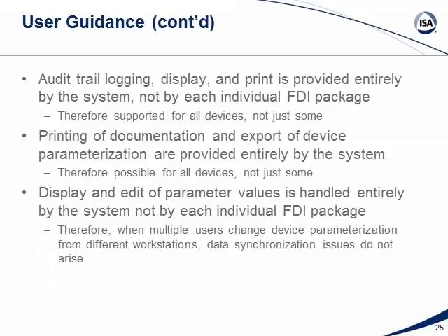Now there are a lot of other strengths to consider, and other process requirements. Audit trails are very important, because in the end you want to know who made what changes and all that stuff. The nice thing about the EDD is that it's the system, your control system or your asset management system, that really takes control of actually configuring the device, using the hints that the EDDL provides. And therefore all the rules associated with audit management and permissions are right at the system level, not programmed explicitly from an FDI package.